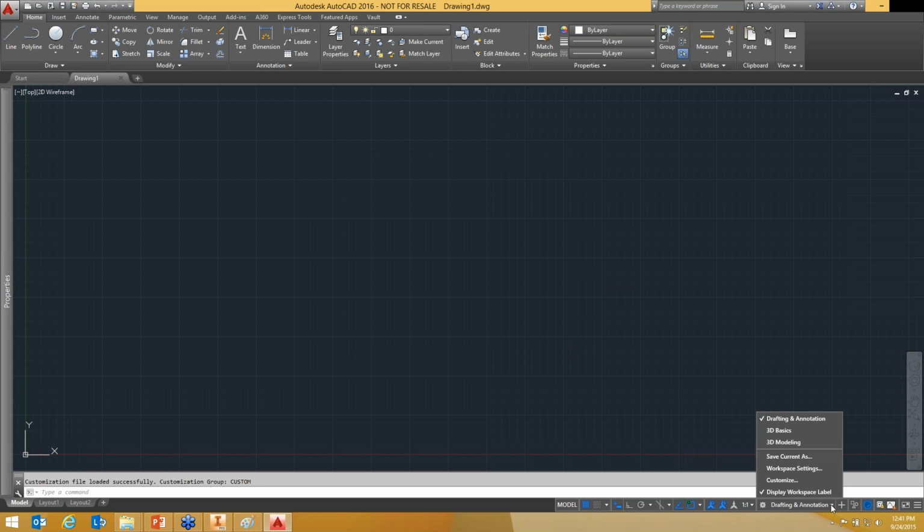Now, where we go to correct this is down into the workspace settings, and it's a surprise to me, but I still run into a lot of folks that are not familiar with the workspaces. And so we've set up to do some unique things here with our workspaces. Now, you could have done all this without going and grabbing that menu file, but particularly if you're more on the administration side, you want to centralize and do things in particular menus that people are loading all up, maybe make an enterprise menu, then you'll want to go through a couple of those steps there as I showed you, to start with a nice fresh menu file that you can begin to put all of your customized things into.